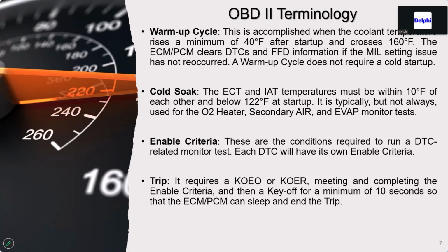Secondary air, almost all the secondary systems that I can think of require a cold startup. And it's usually only very effective in the first few seconds of the startup. Evap, some do, some don't. For cold startup, this is mandatory for evap when you're doing vacuum decay, but some of your key-off systems don't rely on that anymore, because they're doing preliminary tests with the engine warm, and then they're finishing off with small leak detection when the engine's off.